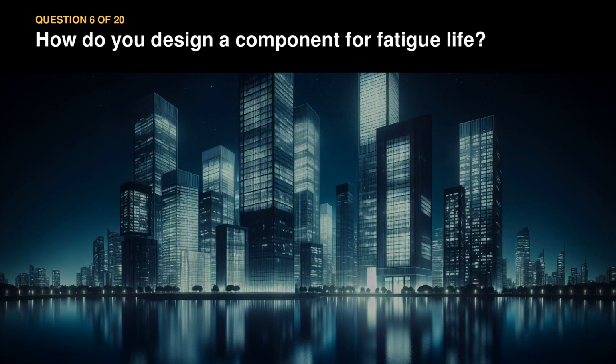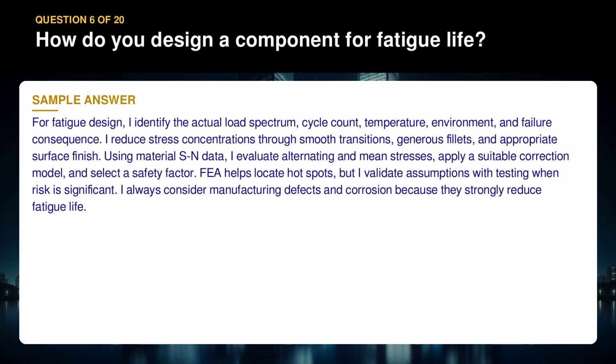Question 6. How do you design a component for fatigue life? For fatigue design, I identify the actual load spectrum, cycle count, temperature, environment, and failure consequence. I reduce stress concentrations through smooth transitions, generous fillets, and appropriate surface finish. Using material SN data, I evaluate alternating and mean stresses, apply a suitable correction model, and select a safety factor.